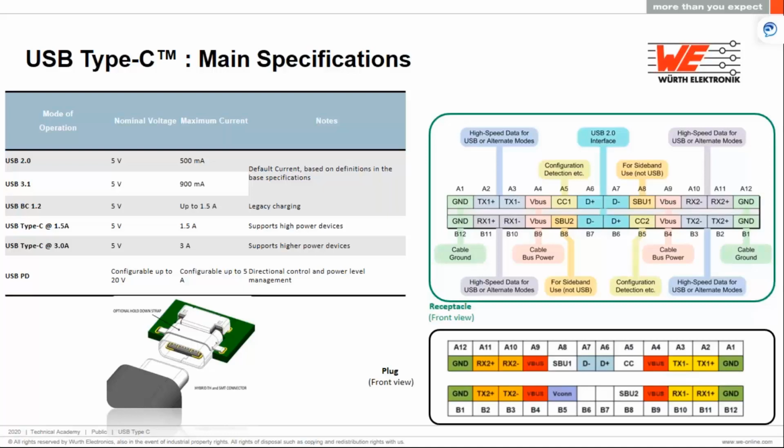That is why usually these B6 and B7 pins are not connected at all. But nowadays, with newer connectors coming up, you'll notice that these plugs come with 24 pins. What do they do in this case? They add a small multiplexer IC behind this connector, which can help us divide the signal, making it possible to use this connector even with 24 pins, or the 2 extra pins.